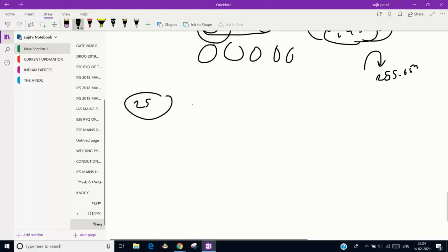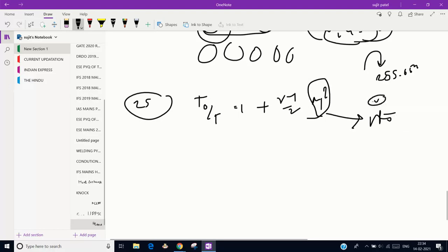Okay, next question that I remember is from fluid dynamics, compressible flow. That is a very basic question. In one question we have to find the stagnation temperature, that is T0 by T is equal to 1 plus (gamma minus 1) by 2 into M square. M is the Mach number, and for the Mach number, the gamma, R, T values and velocity value are given. From that you can find it. In another question, the Mach number value is given, and gamma, R and T are given, so from this equation you can find the velocity. We have to find the velocity of the object.